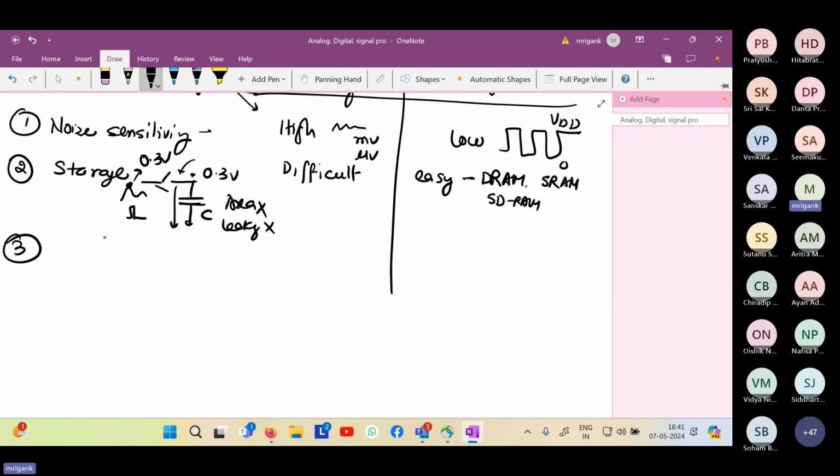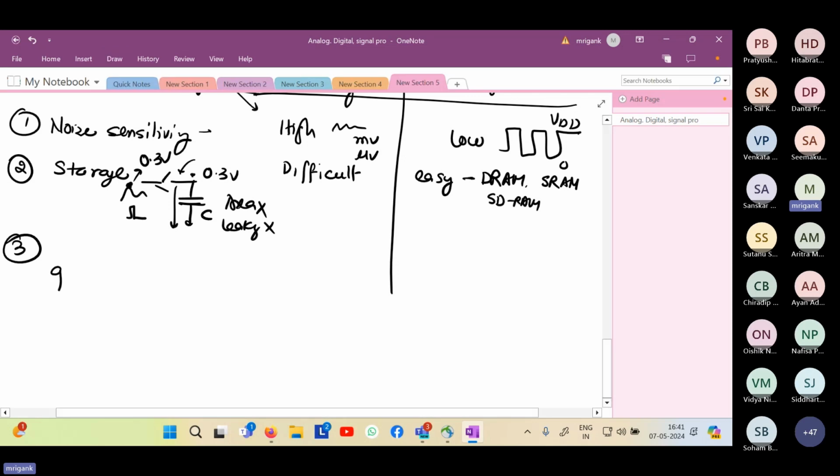Basically, in an op-amp, for example, I guess a two-stage op-amp, I'm not sure whether you have covered it, but ultimately in a single-stage amplifier, a common source amplifier, the gain is something like gm times ro. And gm as well as ro depend upon many device parameters and temperature also, like mu n, Cox, W, L. So all these device parameters are going to vary from device to device.